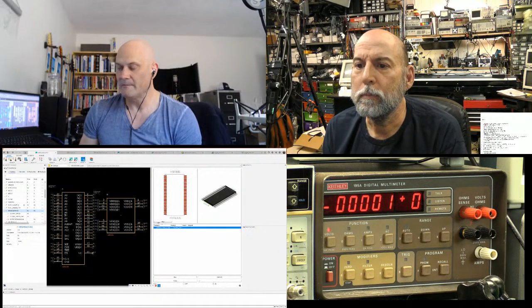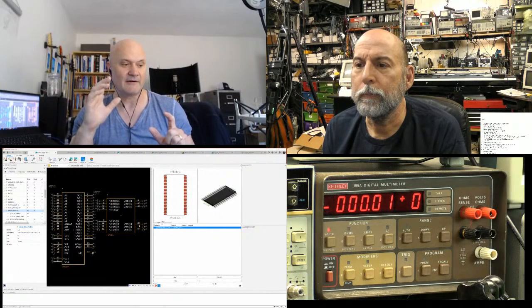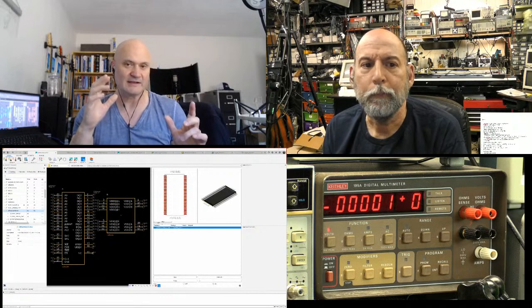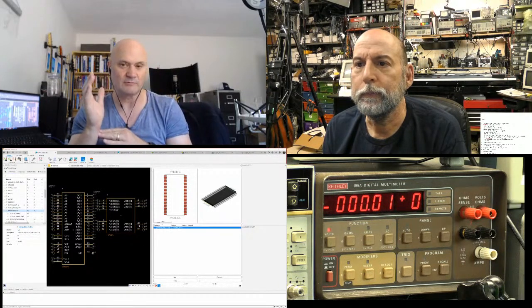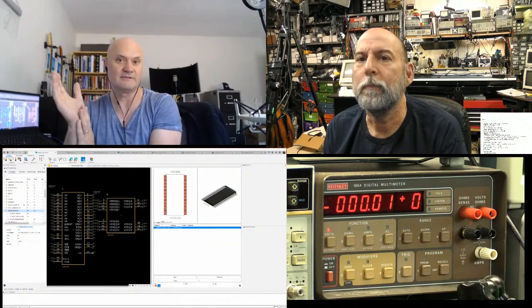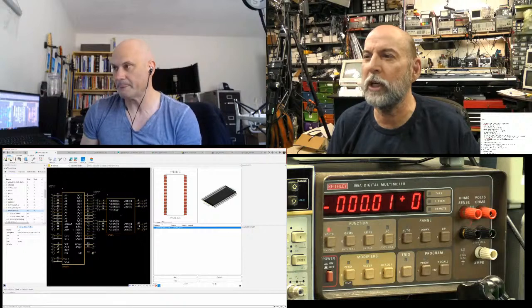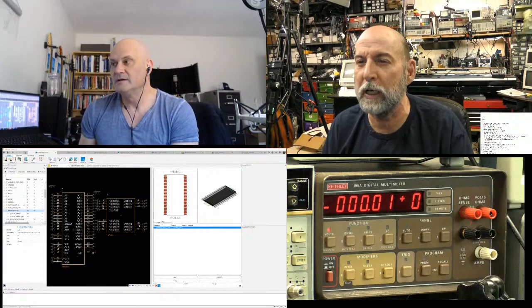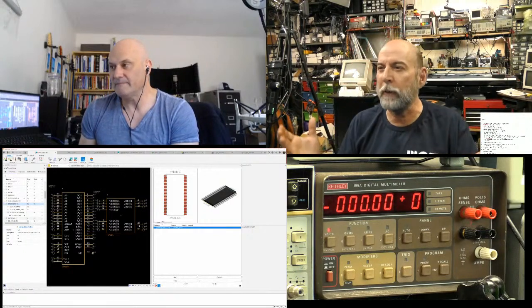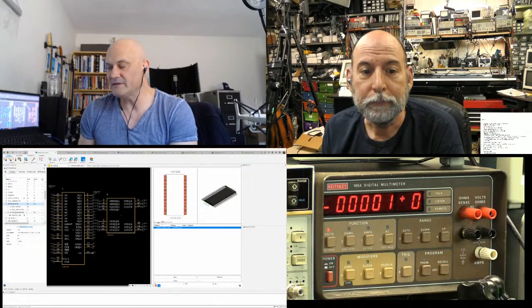And so I did put those on the I/O banks that are based on the reference designs I looked at. There were some particular I/O banks that were good for attaching to memory, so they're on that side of the chip for that reason. And there are even suggested layouts from the vendors sometimes, in their app notes. You might as well pin it out like they have it, because you know it works. Yeah.